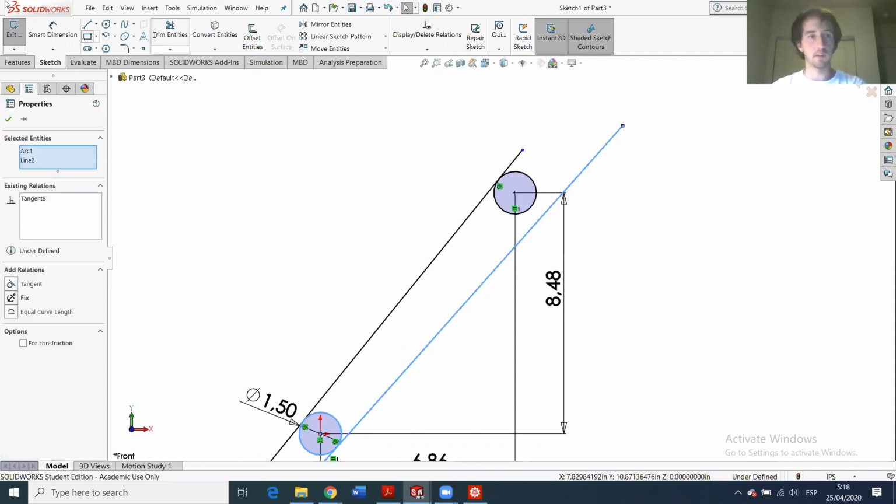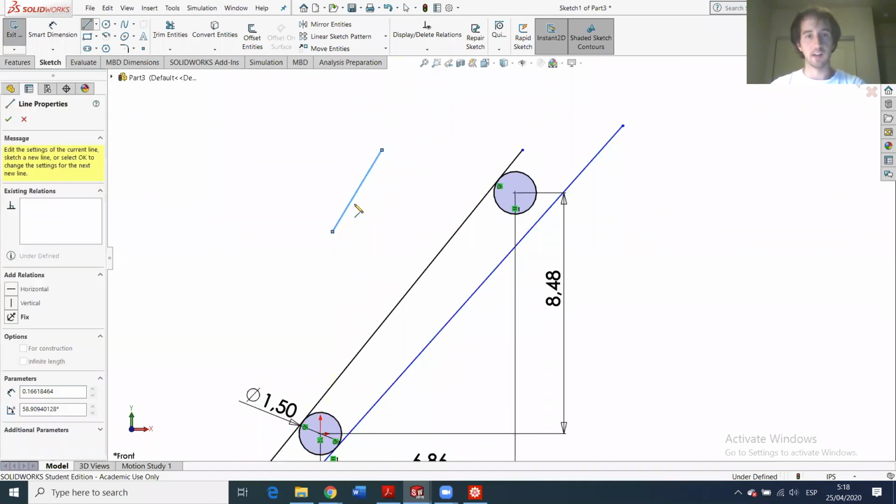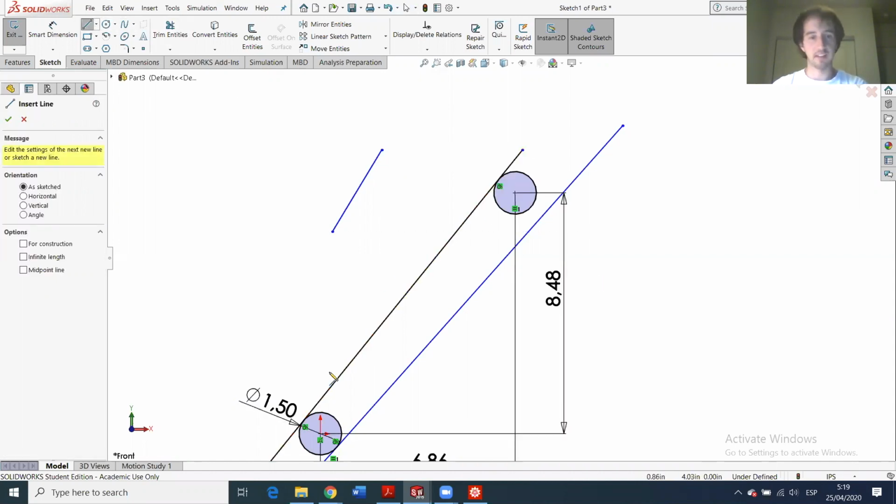And the same happens, for instance, if you start from here. I don't know when exactly it happens, but sometimes if it was a dashed line between here and here, it could understand that these points and this point and this point must be horizontal. And when you modify this, then it will modify also this. So be careful, especially when you want to make tangents and everything, that when you design, you don't start with any dashed line if you don't want.